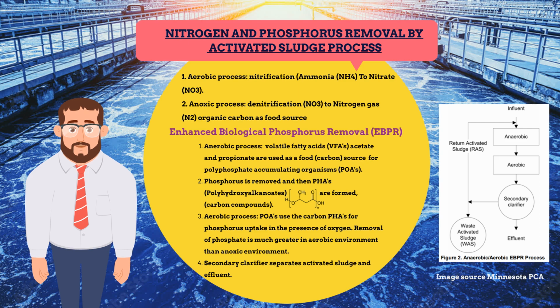The activated sludge process also allows for the removal of phosphorus. The process follows aerobic and anaerobic processes known as EBPR, where microbes use the phosphorus in the aerobic phase and release it in the anaerobic phase. This release increases the energy in the system, to be used in the uptake of biochemical oxygen demand, BOD.